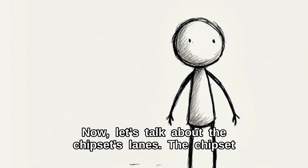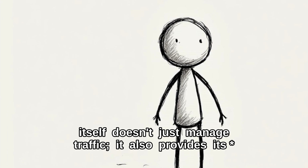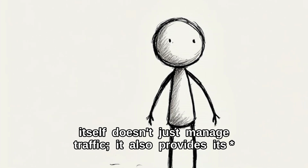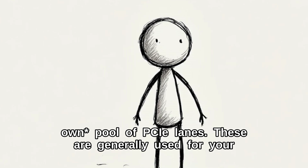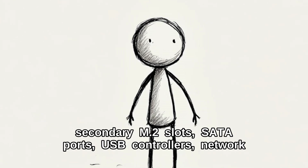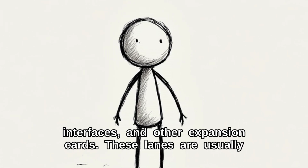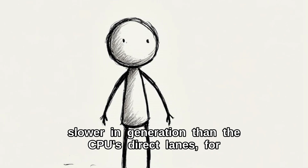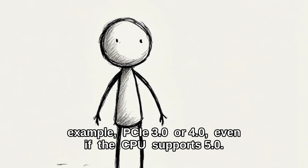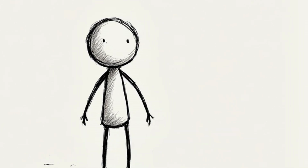Now, let us talk about the chipset's lanes. The chipset itself does not just manage traffic, it also provides its own pool of PCIe lanes. These are generally used for your secondary M.2 slots, SATA ports, USB controllers, network interfaces, and other expansion cards. These lanes are usually slower in generation than the CPU's direct lanes, for example, PCIe 3.0 or 4.0, even if the CPU supports 5.0.